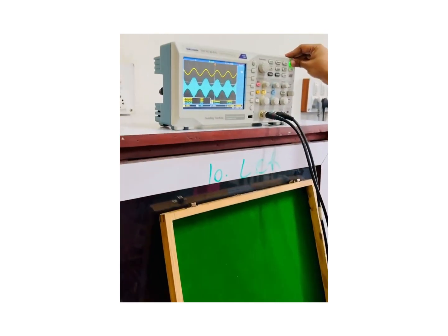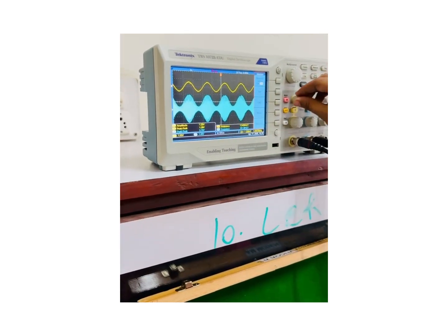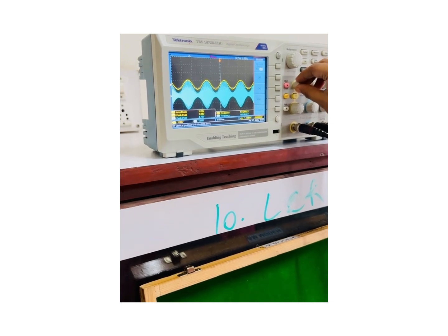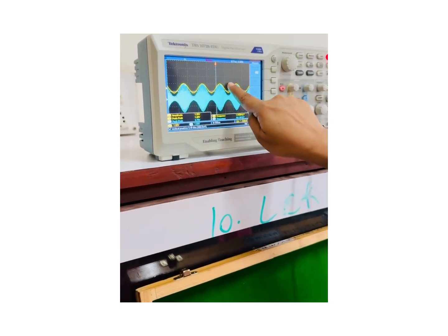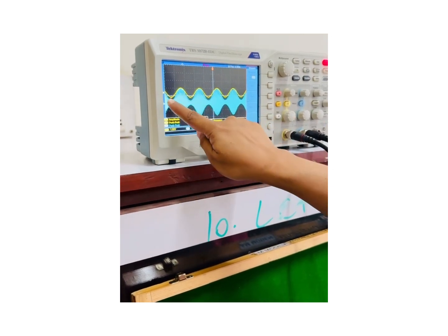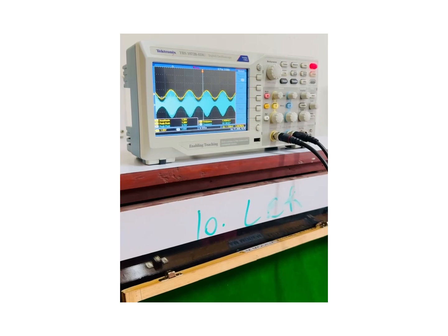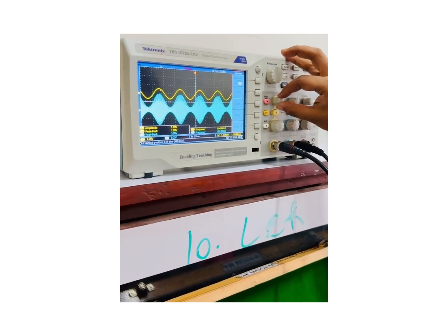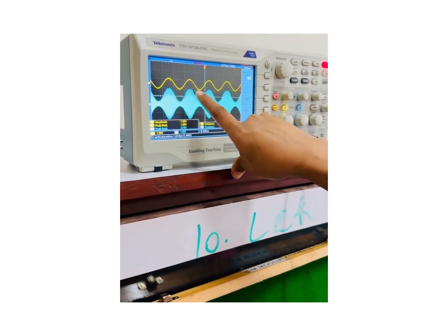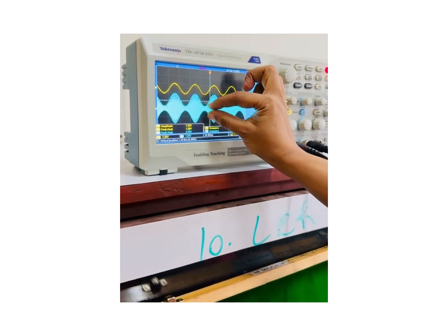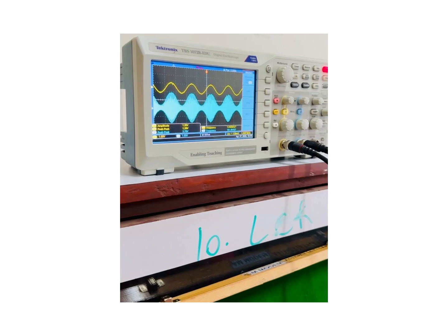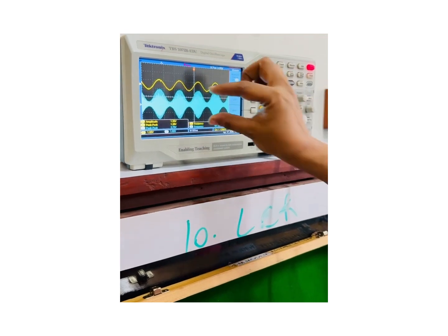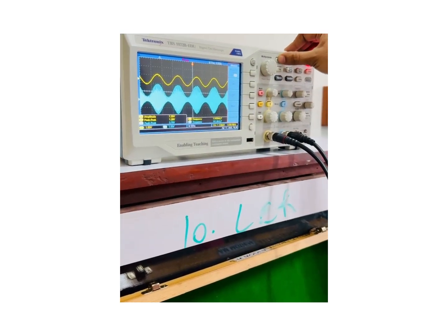Now in this envelope of the modulated signal, we can observe that the edges of the modulated signal carry the information, or the modulating signal, and on the receiver side this boundary of the modulated signal will be extracted to get back the original modulating signal. We can measure the modulation index using graphical method by measuring the voltages of Vmax and Vmin, and using the formula modulation index is equal to Vmax minus Vmin upon Vmax plus Vmin. So to measure the value of Vmax, we need to use cursor.